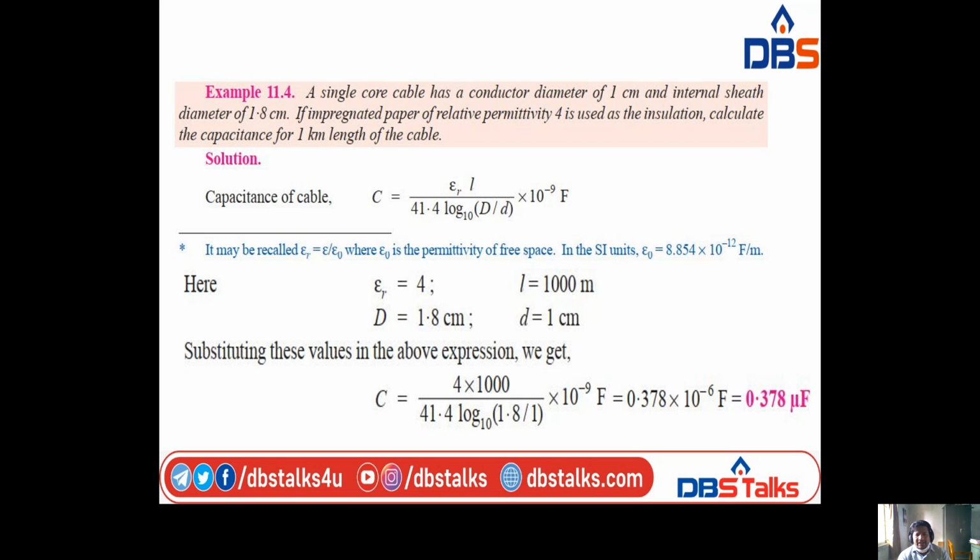Next problem, a single core cable has a conductor diameter of 1 centimeter and internal sheath diameter of 1.8 centimeter. If impregnated paper of relative permittivity 4 is used as the insulation, calculate the capacitance for 1 kilometer length of cable, right? Capacitance of single core cable, capacitance of a cable C is equal to epsilon r L by 41.4 into log capital D by small d.